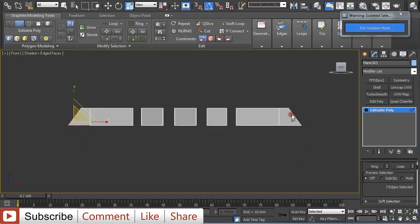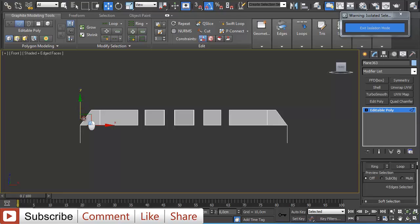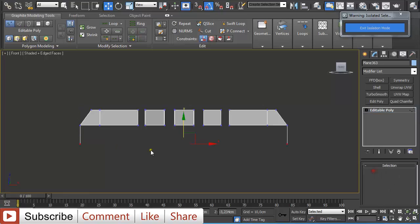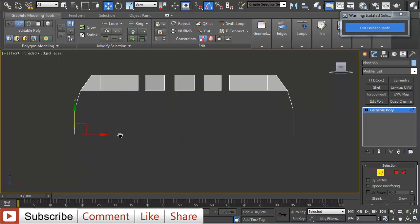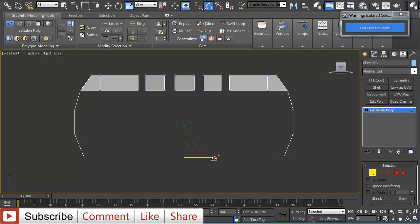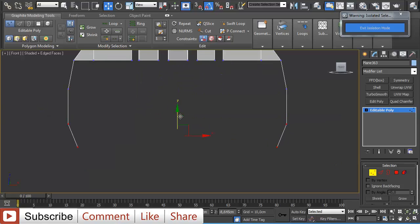and then just selecting these edges, and by holding shift I'm creating new ones, and then holding control and switching to vertex selection, and move them out a little bit, go back to edge and just draw it out once and twice, control vertex R and move it inwards a little bit, then just reposition this outer mantle that I just created.